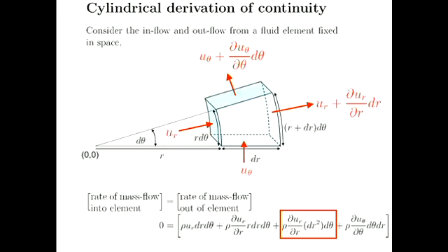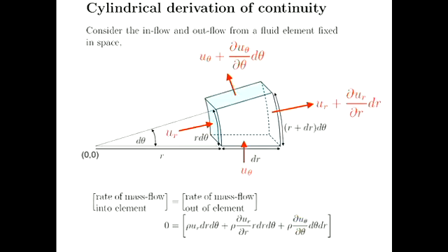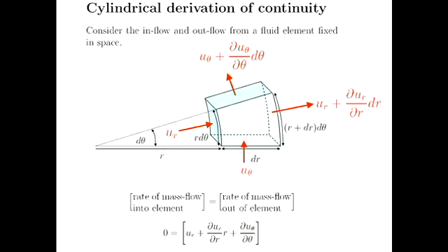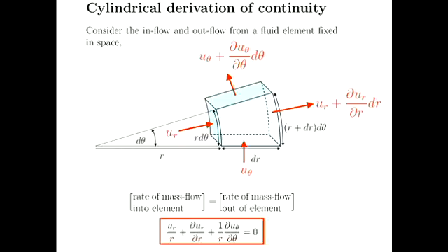You're familiar with doing this from other courses, right? These equations, especially in the latter part of the course, are going to get really nasty. But by recognizing which terms are insignificant, we can keep everything manageable. So when we get rid of that term, we see that everything else has this rho dr d theta in it, which we can just get rid of. And very simply, this version of conservation of mass in that cylindrical polar coordinate system drops out. So does that make sense?